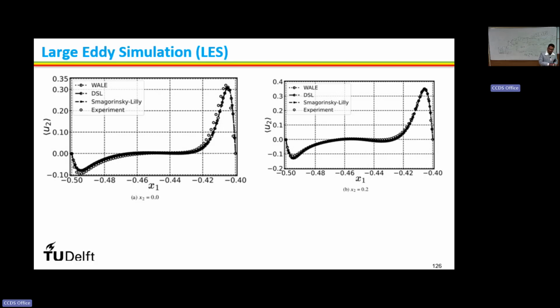Once you do the LES, in result post-processing, you can see there are a lot of things like the Q criterion, this lambda criterion, to visualize the vortex structure, etc. You can see the small scale eddy movement. All those things we can see today in the hands-on training, right? This will give you the information on the flow transition. If there is a laminar flow, then the flow undergoes transition, then the flow becomes turbulent. We can see it from the visualization of the streak line, the burst of the streak line.